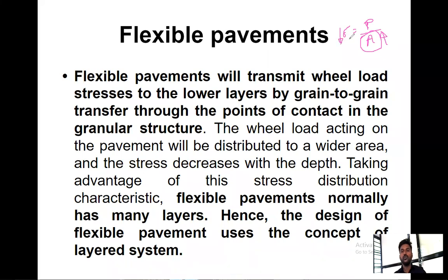So we need to distribute the stress over a wider area, so that there will be less stress generated on the soil. If the depth of the pavement is more, it will give a wider area to distribute the load. If a wider area is there for distribution of the load, there will be less stress produced on the soil.